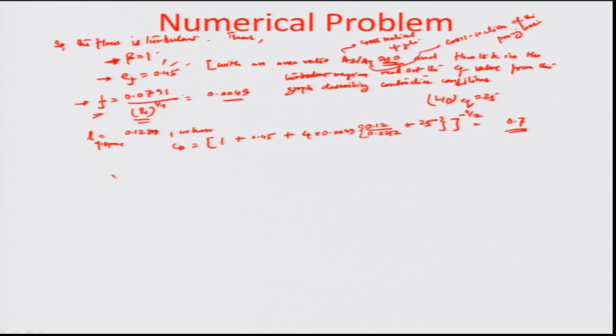So, therefore, the V3 dash or the velocity is going to be the CD times root 2 g h t, as I had earlier illustrated with the formula from the energy balance with friction. So, this is 0.7, that is 70% of the ideal case, which was 1.716 meters per second. So, this comes out to be about 1.20 meters per second. This is not the end of the story, because we will have to iterate to recalculate. So, actually the velocity is not 1.716, but 1.2 meters per second.